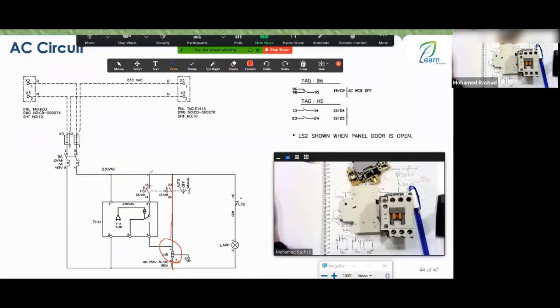When this closes, the supply will come from here, pass through the heater, which is connected to the neutral from here, and it needs the live. Of course, this is open. So the live comes down here. Yes, it comes down to pass through and go here. This contact must be closed. Which contact is this? As you can see, this triangle symbol is a comparator symbol.